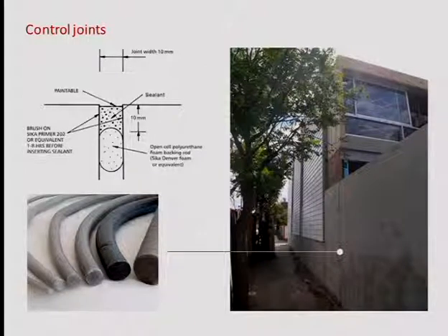And that is partially true, because when you have a wall like the MAXXI Museum in Rome, which is 16 meters high and 25 meters long, then you have a problem. It's not so monolithic, and you can't really build it that way. So you need to separate it in parts and portions. So somehow your idea that concrete or blocks can make very monolithic, huge volumes is only partially true. So they have to be divided anyway.